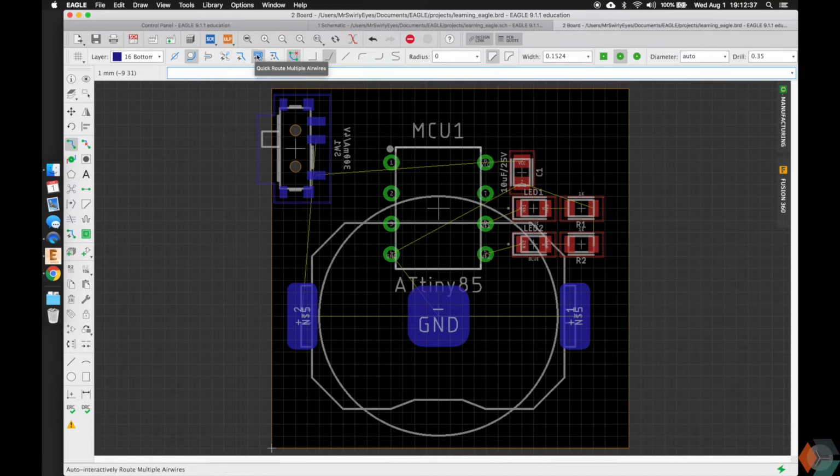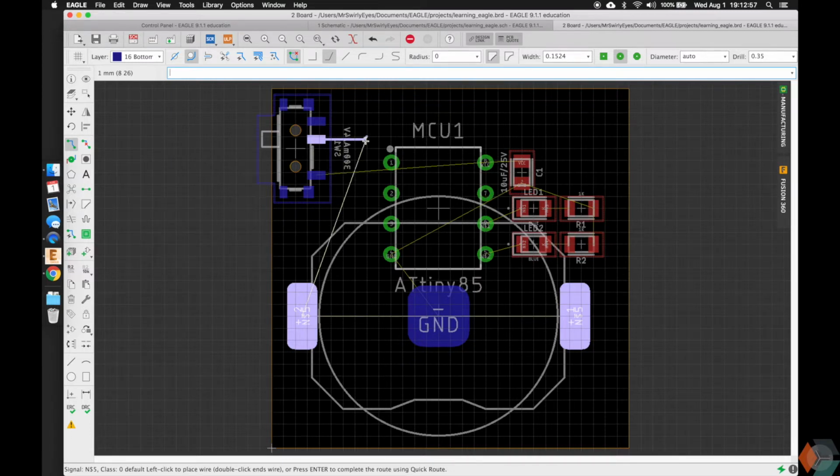There's some other options that you might want to explore. It can help push wires around other wires if you're routing them. There are wire bend styles, just like there were in the schematic. Here, I would recommend using wire bend style 1, which pretty much means 45-degree angles, for a couple of reasons. The first is manufacturing. When the manufacturer manufactures your board, it actually prefers to have 45-degree angles and not abrupt right angle turns. That's just what I've read up on. The exact reason I'm not 100% sure, but I heard 45-degree angles are better for the CNC machine or whatever machine they're using. Also, in terms of actual electrical behavior, this is not a high frequency circuit, but if it were, wires at 45-degree angles or even these meandering wires are better for reflections at high frequencies.